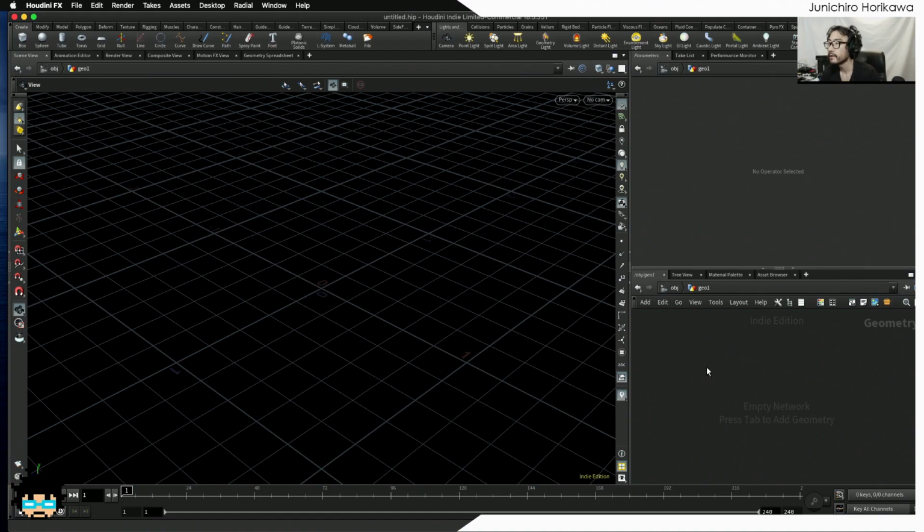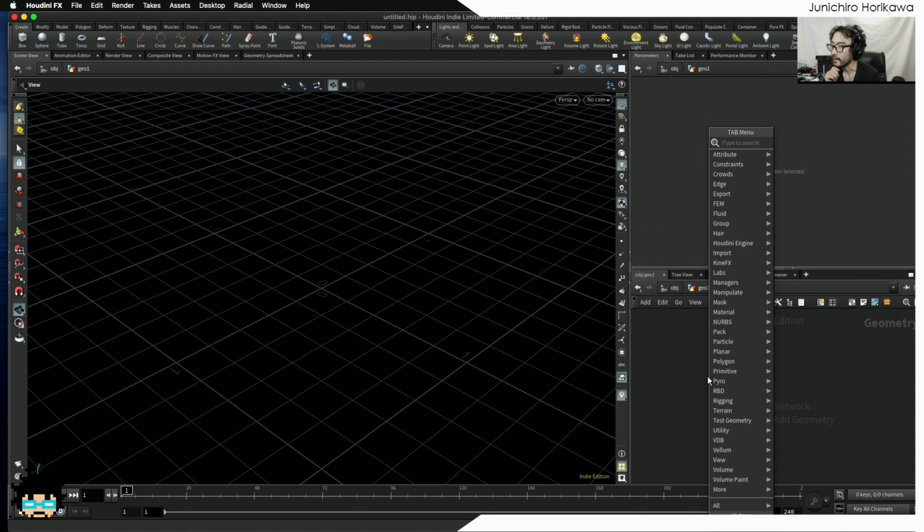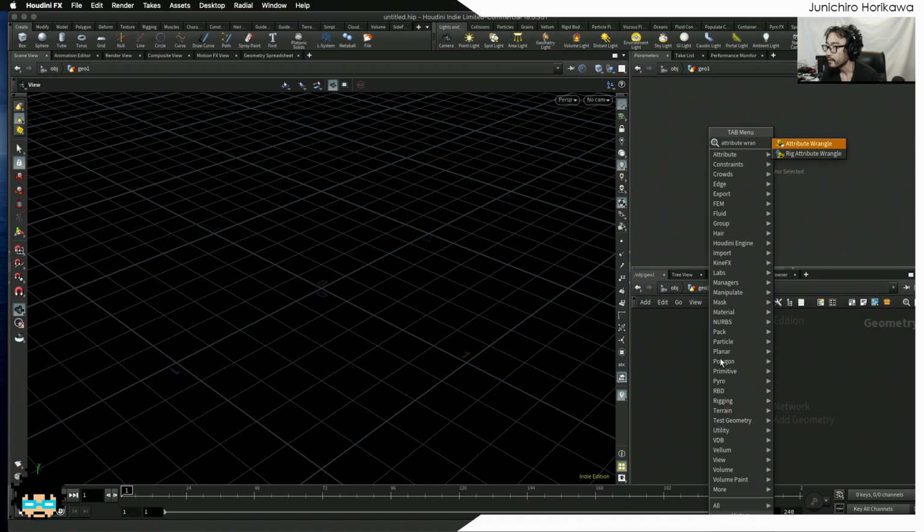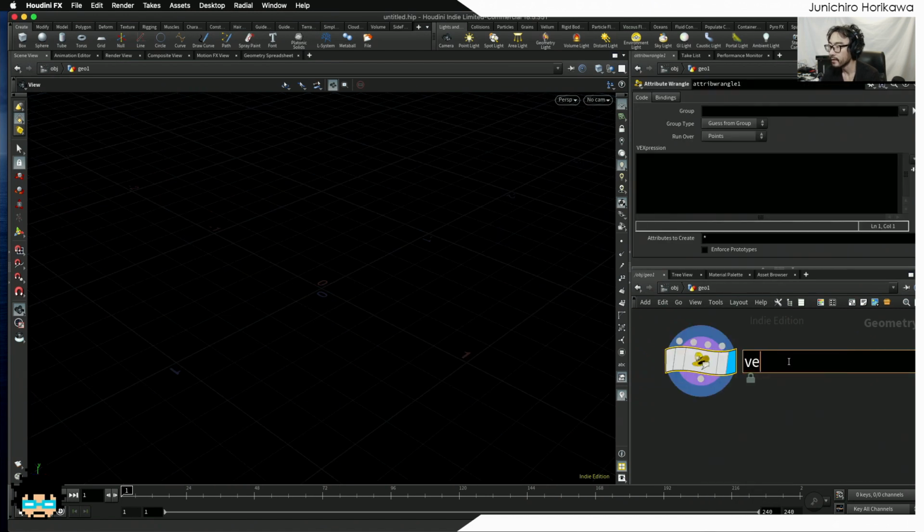The first thing first, let's see how you can declare a quaternion. One of the ways is to just use a vector4 variable to create a custom quaternion value by yourself. Let's use an attribute wrangle, and I'm gonna change this to detail. Let's say vector4, and I'm gonna set the name of the variable as val and say set 0, 1, 2, 3.